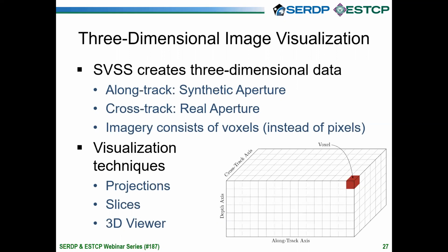Now one technique that we use, and that is used by other groups that do this, is that we use multiple transmitters distributed across the sonar system, from port to starboard. By doing that, we can achieve a boost in our real aperture resolution, but still not to the same level as our synthetic aperture resolution.